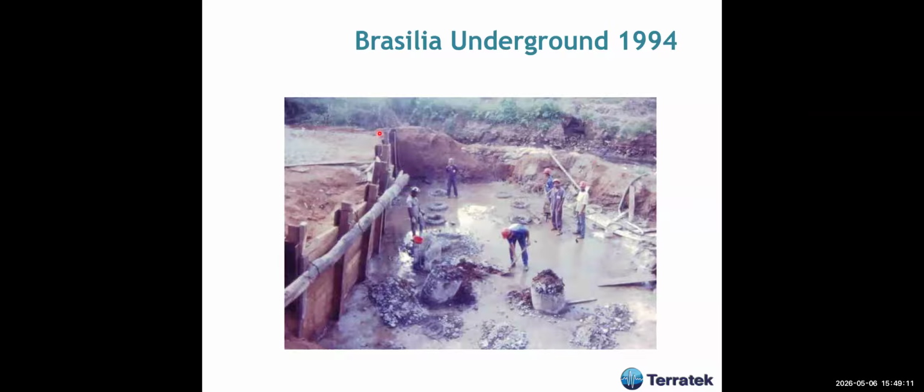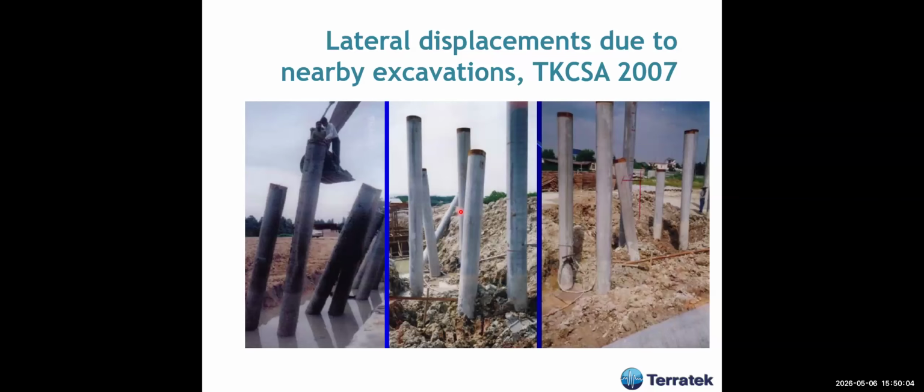I told them, before they start excavation, not to do that without proper design for the excavation. Because there were soft clays and embankment soft clays, when they started excavating, some of these piles tilted like this one. So they had to be replaced.